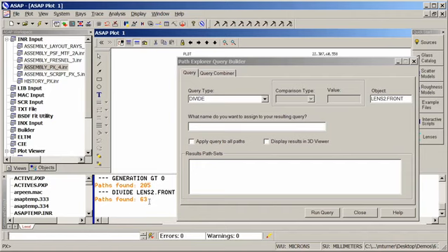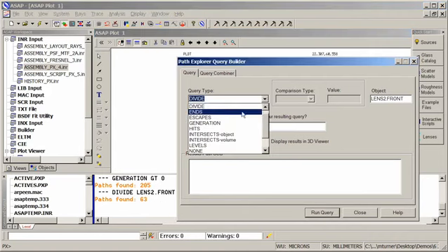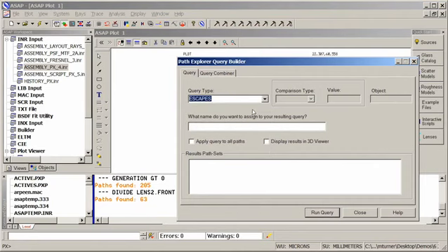This is going to include both first order ray splitting as well as second order ray splitting because I have allowed that in my ASAP script. So the next thing I want to do is eliminate any of the second order paths that actually reach the detector. And the way I'm going to do that is to select the query type of escapes.